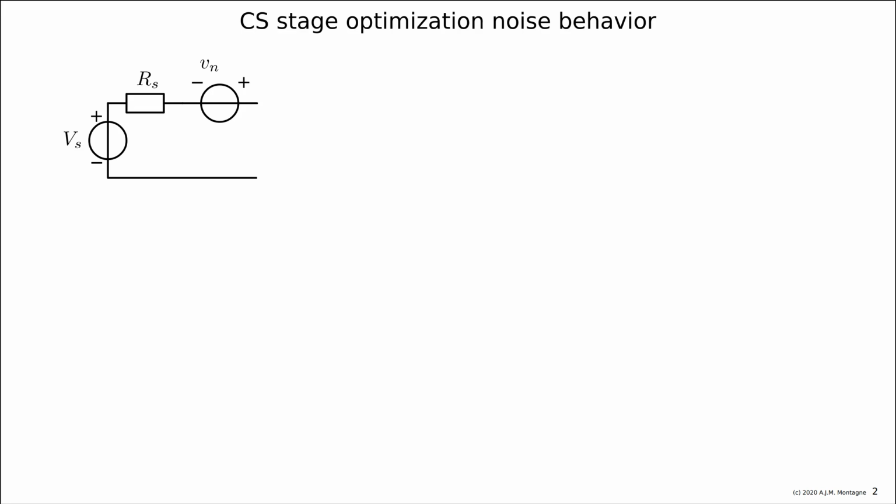That is very important, so you don't need to try. If the optimum is not good enough, then it cannot be made. And we will find out that probably you need a process with a higher FT, because the optimum is related to the FT of a process and the maximum frequency you want to operate at.